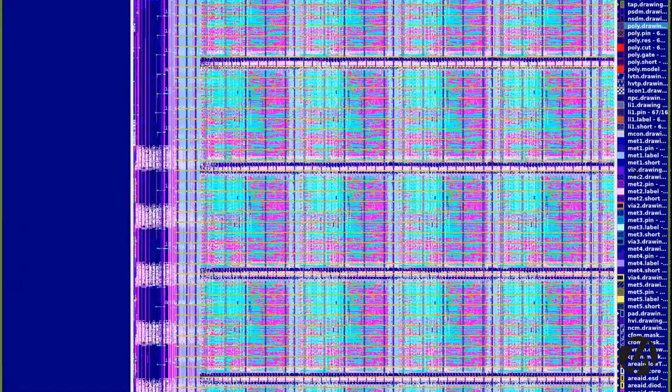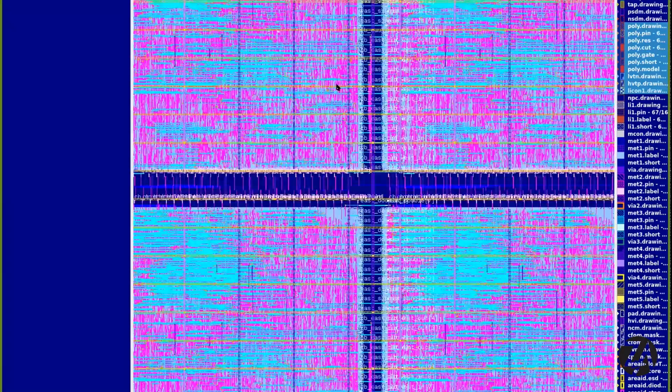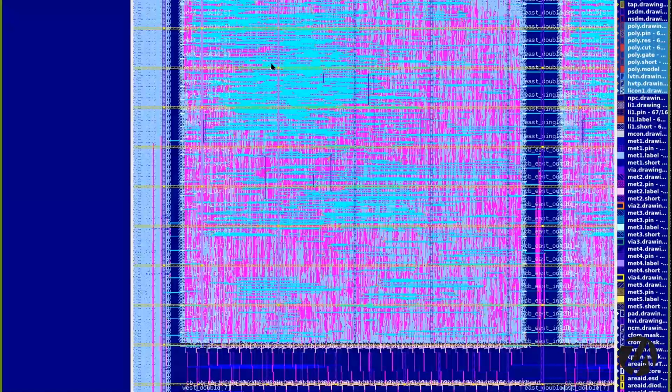Okay, so each one of these big squares is that set of 4 blocks, is it? Yes. So this is a configurable logic block, which is the LUTs that you mentioned earlier, and some switch boxes. Well, 1 switch box which connects it to its neighbor, and then 2 connection boxes. Can you zoom in on that for us? You can't really tell the structure by looking at it, though. There's clearly like a massive, highly interconnected area, which I suspect is the switch box.